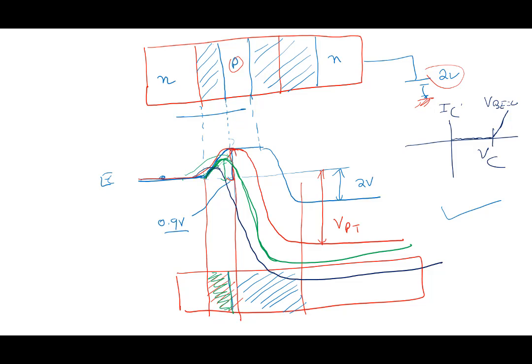So many times in the transistor, there are two things that can happen here. It's a reverse bias junction. Either the junction may break down or punch through. Both of these things will make the transistor conduct in the reverse bias case, which is not the required thing, which is something that you need to avoid.